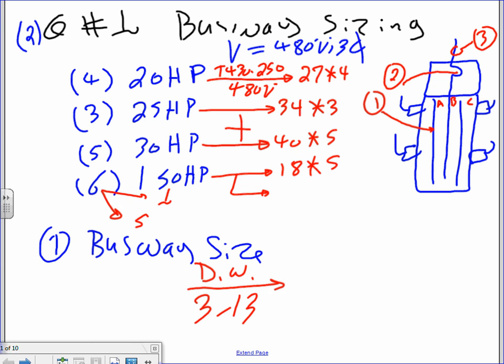So you take 180 first and multiply it by 5. You take 5 of them and multiply it by 180, and the last one, 180, you multiply it by 1.25. Everybody knows why I split this one into 2? Because you take one of the largest motors and increase it 25%. Not all the largest motors, one of them. The rest, which is 5 of them, are right here, right? Makes sense? And then you add them up.